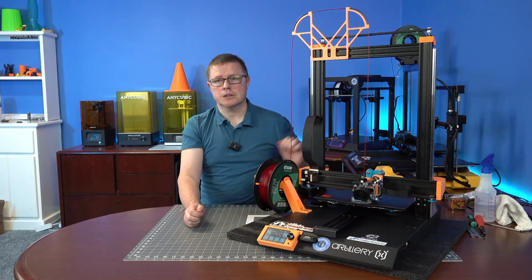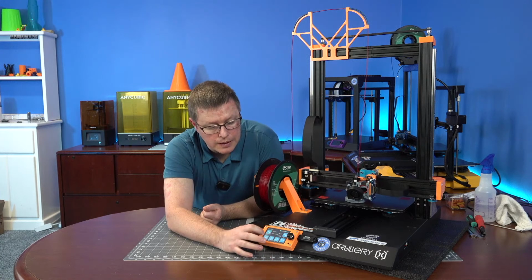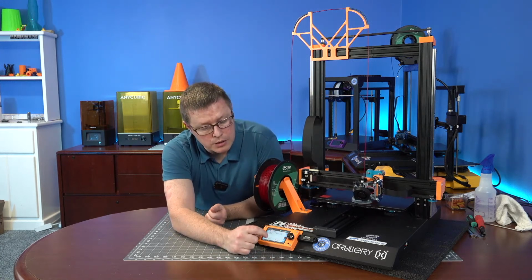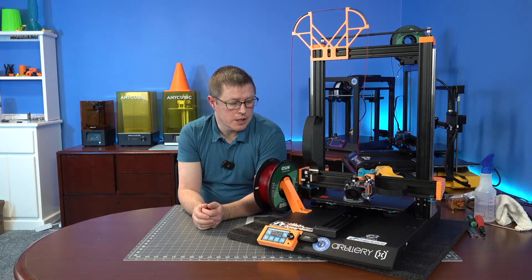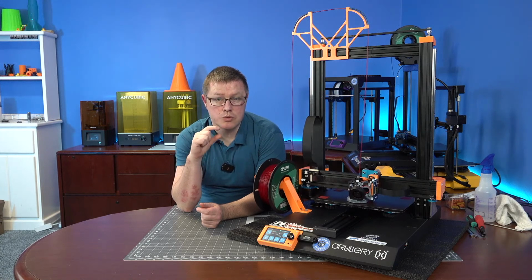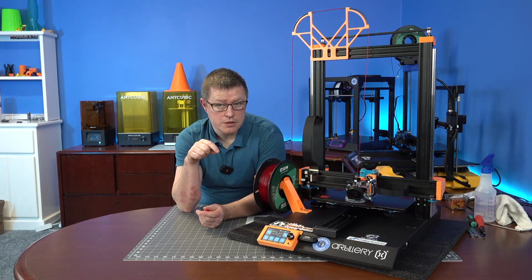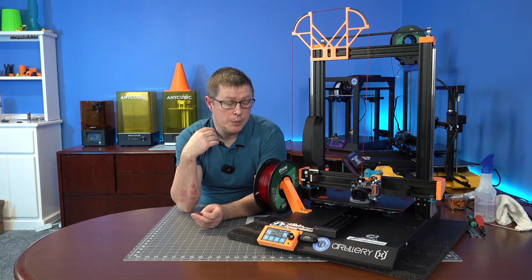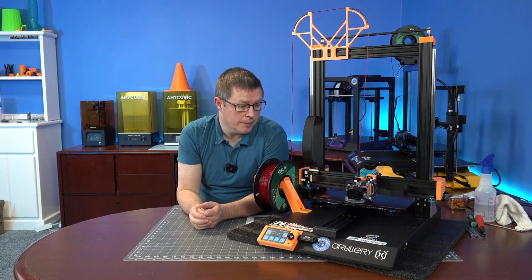Drew says back to that Sidewinder mount and fan duct question, I was looking for more layer height infill parameters. Oh, okay, so layer height 0.2. I wouldn't go any thicker than that, just because the height of the model is drawn to that layer thickness, because it's divisible. I do 5 shells, and I believe I did 30 or 35% infill. I wouldn't go any less than 30, and you can go to the moon with it. And no supports necessary.